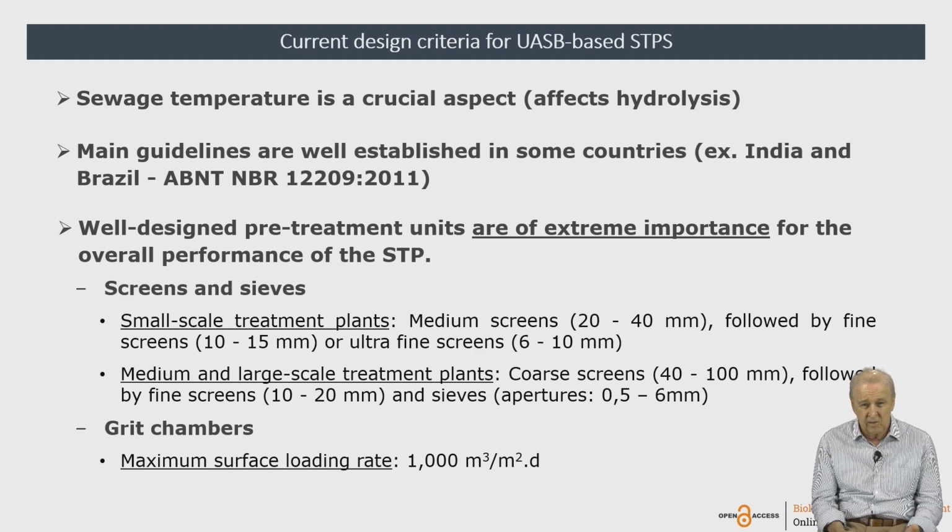It is almost impossible to heat the reactor when treating domestic sewage because the flow rates are usually very high, and the concentrations of COD and BOD are proportionally low in comparison with industrial effluents. So it's almost impossible to heat up the reactor when treating this liquid phase.